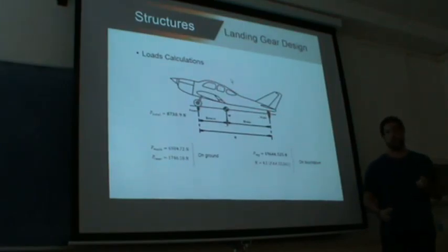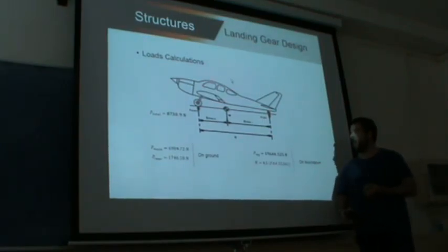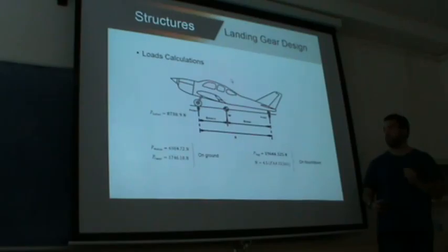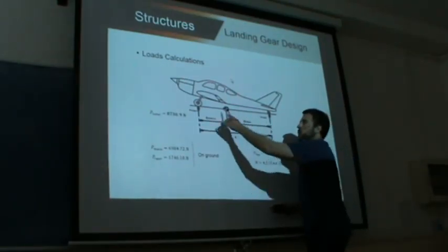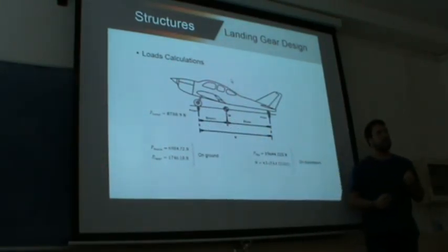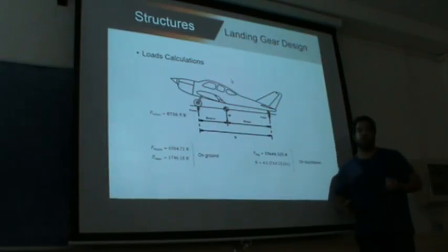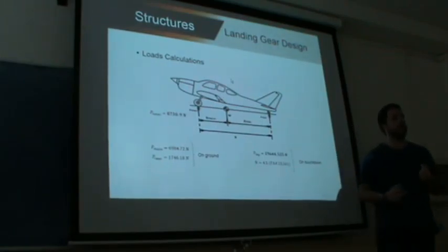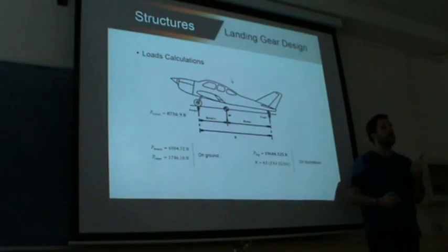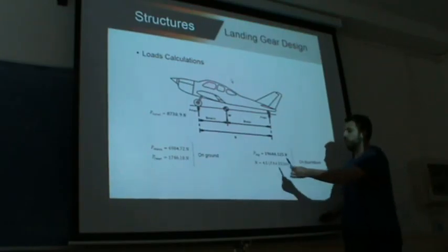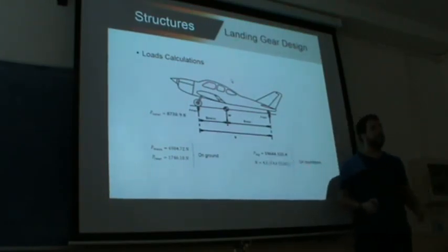When the aircraft does the touchdown, all the load is concentrated in the main wheel, multiplied by a security factor. Well, not really a security factor, but what is called the landing gear load factor, which is 4.5. That is regulated by the FAA.